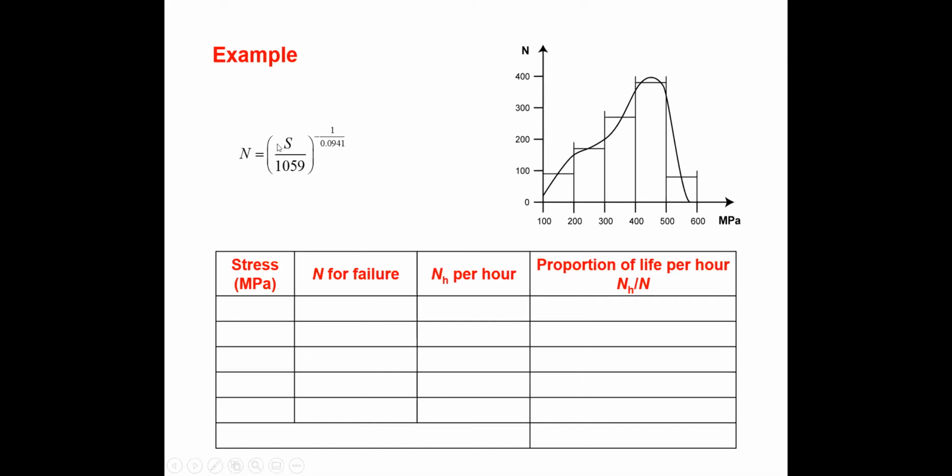So this is the equation. Only above the endurance limit is Miner's law applicable. We can only use Miner's law above the endurance limit. Why Miner's? Well, because Miner's law is, if it breaks, the sum is equal to 1. Miner's rule. Okay, a Miner's rule.